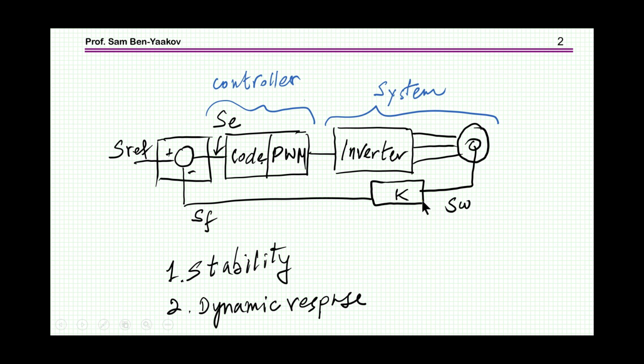In this case, I'm showing the speed of the motor through some conversion constant, converting, let's say, the speed coming out of a tachometer into a voltage, and then comparing it to what I want. This is the reference, this is the command, this is what I want, and generating the difference.